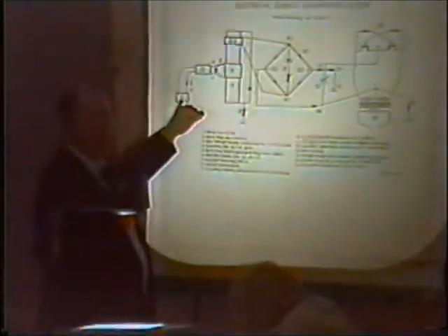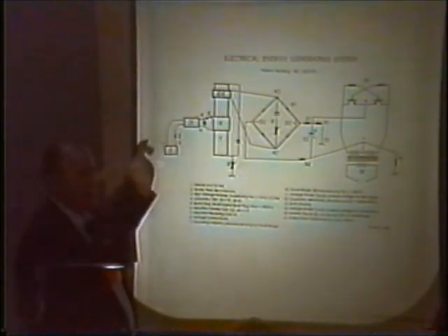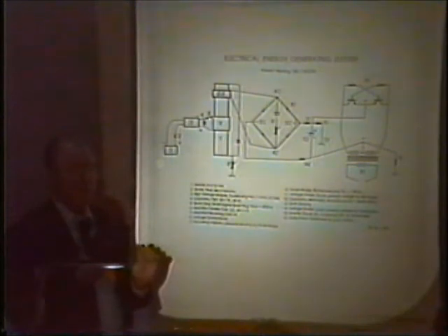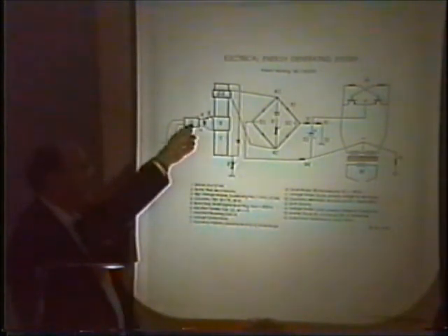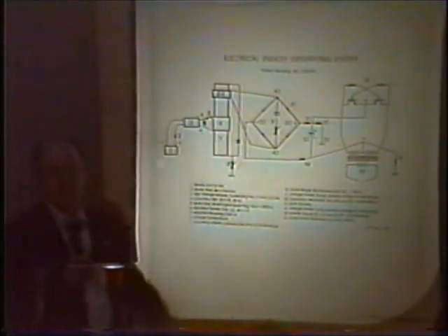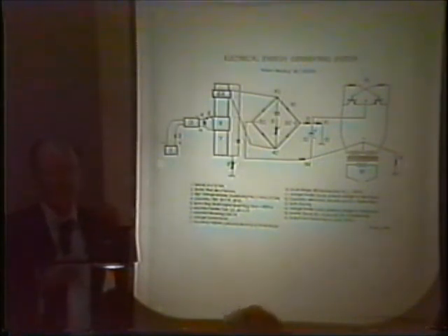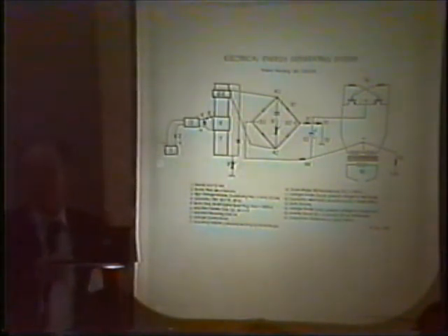Of course, here's your gel cell battery. Here's a diode that you put on your plus side so that you don't get a kickback. If you get a kickback, it damages your high voltage module. The high voltage module is a laser high voltage source like you'd have in your laser printer or whatever. They're available off the shelf, and if you buy them direct, they're a couple of $100 or $300 maybe or something like that. If you're lucky enough to find one in an electronic surplus place, it might be as low as $50 or maybe even lower.